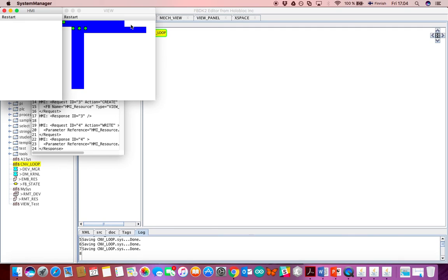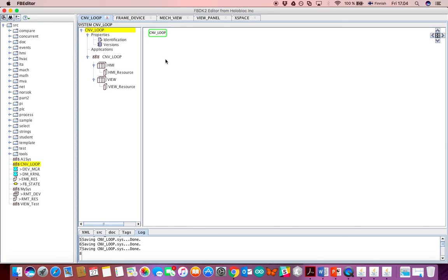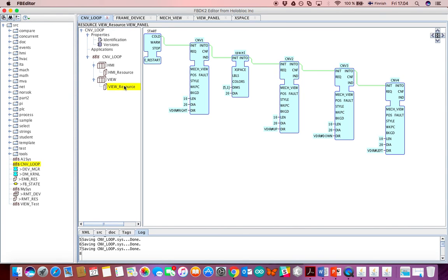You see, it's quite challenging even for me to use this block, but we can now carry on locating conveyor 2, which is now here, conveyor 3 is here, and conveyor 4 here. Again, please look, this is considered as a single row somewhat, and since 200 pixels, 20, 20, 240 is enough to fit in the area of 300 pixels, they are coming now in this configuration. So to carry on, I would need another XSPACE block.